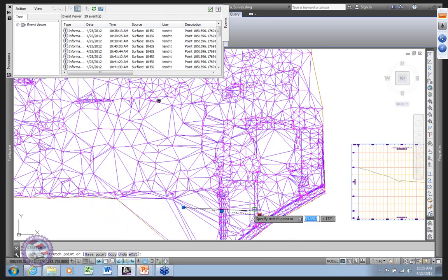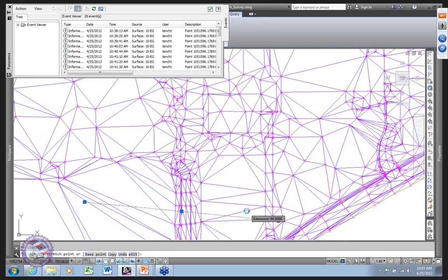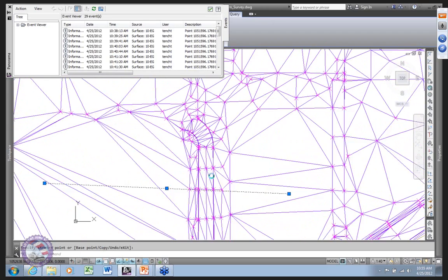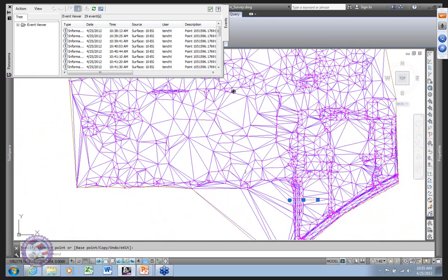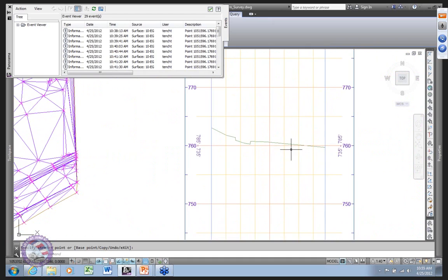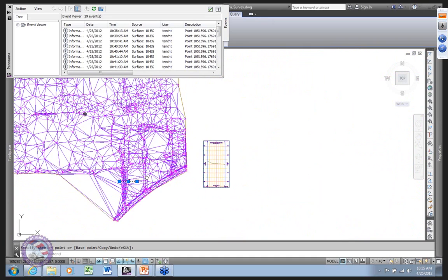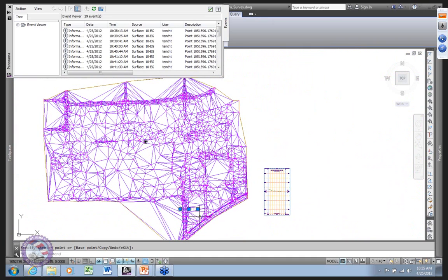And a couple little tricks is I've noticed that in 13, one of the things it tends to do with those quick profiles is you actually, instead of just moving the midpoint, really do have to move one of the endpoints now and then to get it to keep up with you, but it all still works. And once again, delete, all gone.